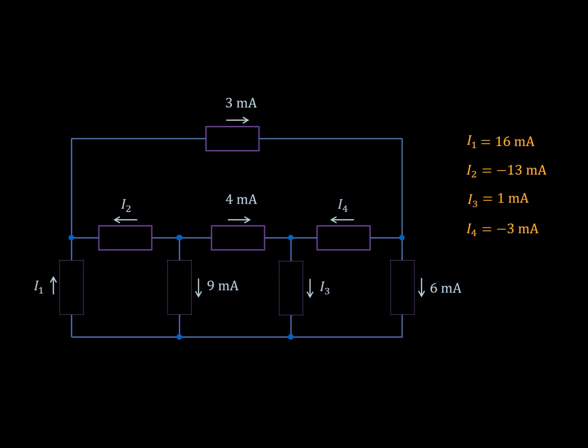In the future, when the equations get messier and require well over 10 steps to solve by using basic algebra, expect me to use Gauss-Jordan elimination instead. Alright? By the way, I know I2 and I4 are negative values, but keep in mind there's no such thing as a negative current. It just means it's going in the opposite direction. If you flip the arrows, then they become positive, but we will leave the negatives.